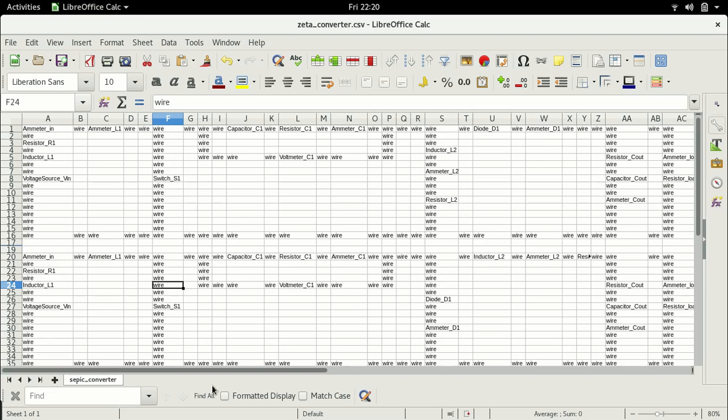When the switch is turned off, let's compare these two. This SEPIC converter now has a forward path. So for example, the voltage source is now connected directly to the output through this forward path, through the decoupling capacitor and the diode. The diode conducts because the polarity of the diode is such that the cathode is towards the right. So the current flows to the right. So therefore, now the voltage source and the inductor are charging the output, this decoupling capacitor and the output capacitor.